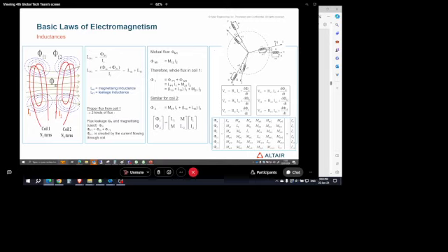So this is the main magnetic flux I produced, and we always have, unfortunately, this leakage magnetic flux. So then we have this self-inductance, which is equal to the magnetization inductance Lm plus the leakage inductance for coil 1.